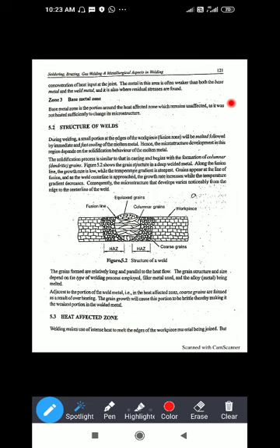So see, we have the fusion zone, the heat affected zone and the base zone. The base zone is stronger from the starting itself. Before welding and after welding there is no change in its mechanical property, it is stronger. In the fusion zone, due to the melting of the two metals, new microstructures and new grains are being generated.